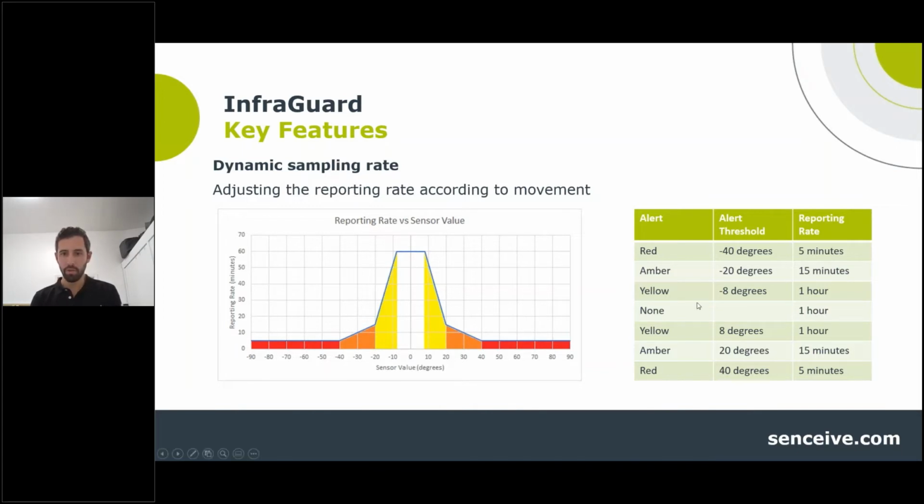So looking on the right-hand side, for example, we can set up a system to report every 1 hour, but we can certainly go much less than that. Just depends on what that requirement is on site. We can go sub-minute on our FlatMesh platform. In this case, looking at a 1 hour sampling rate, which is certainly sufficient, because what's important here is if there is movement, we're going to capture that, right? So we don't have to operate at a very high sampling rate with this system.